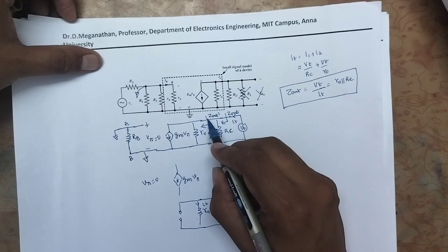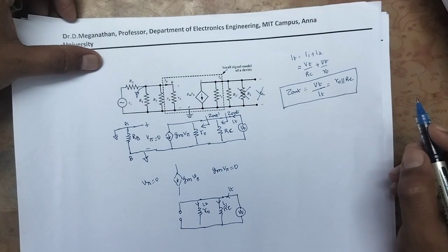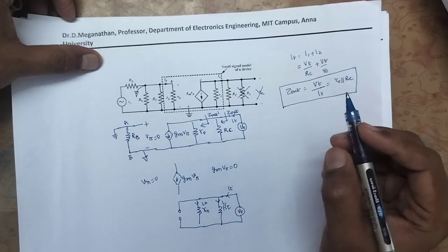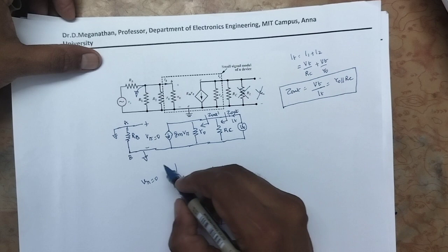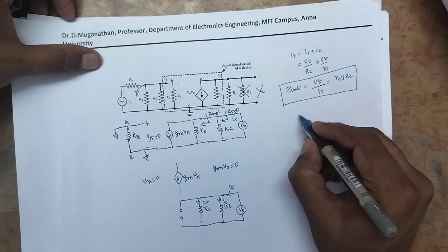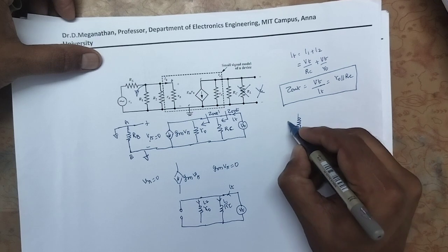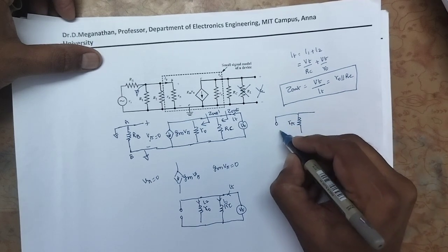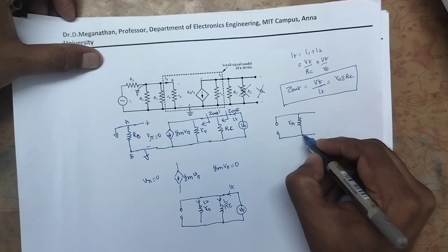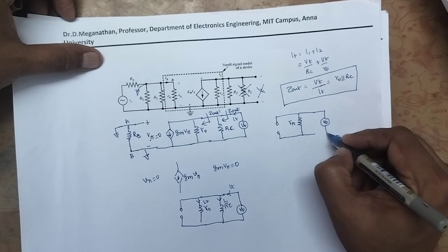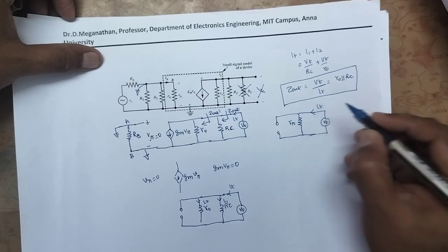So next one is output impedance seen by the collector arm by neglecting the biasing resistance RC. Again same thing, V pi 0, then gm V pi is 0. So what else? You have R0, gm V pi is opened, and we are going to connect the test voltage VT here. That will supply the test current of IT.